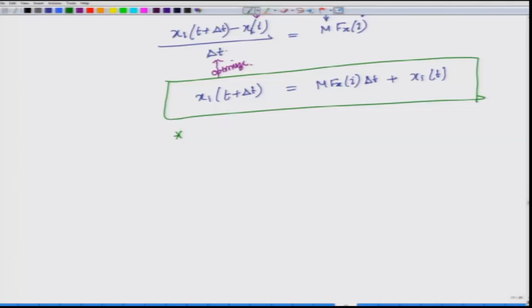So, this can be a very simple problem by making lots of assumptions, or you can make it much more accurate and a little more complex by adding complexities. Like you can add that there has to be a Peierls-Nabarro stress for the dislocation to move. You can say that the dislocations will move only on certain planes, which are slip systems.